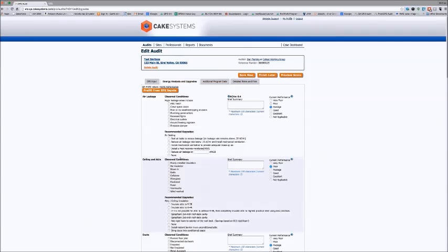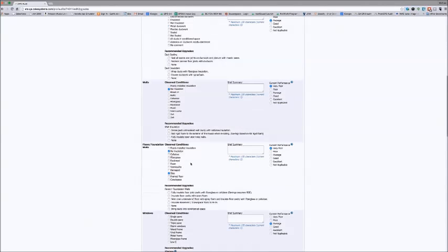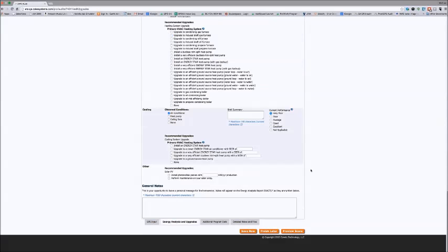But we let you make the recommendations for what kind of improvements need to be made. So reducing air leakage by a certain CFM 50, or scaling it up to the BAS, insulating the attic to whatever levels are appropriate, and going through category by category in each area of the home. Then with these specific upgrades, we know how to do specific energy modeling on them.